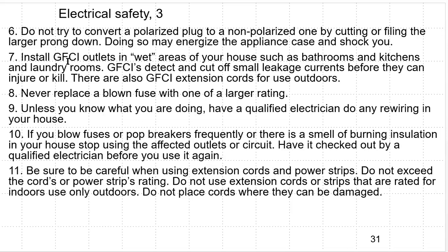Install GFCI outlets in wet areas of your house, such as bathrooms, kitchens and laundry rooms. GFCI stands for ground fault circuit interrupter. They detect and cut off small leakage currents before they can injure or kill you. There are also GFCI extension cords for use outdoors.